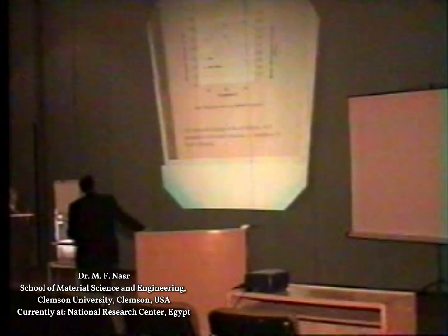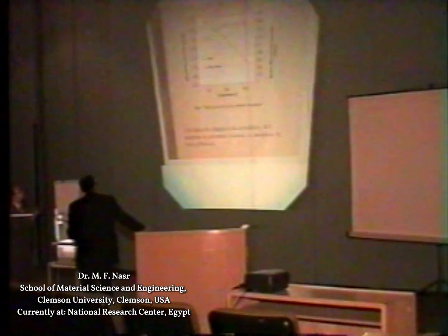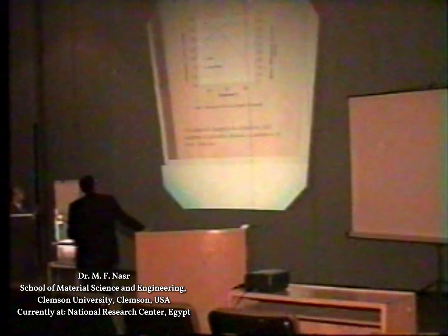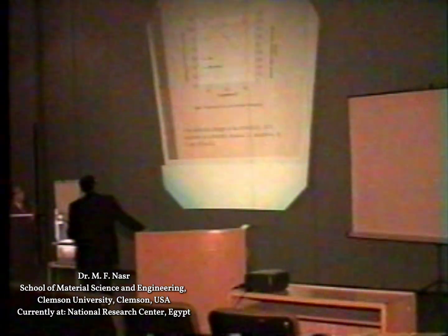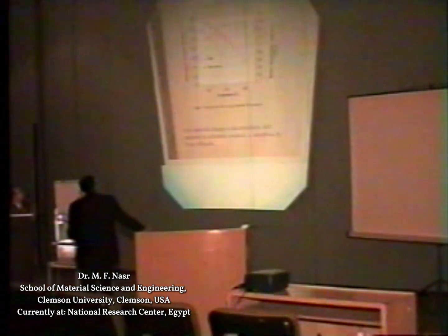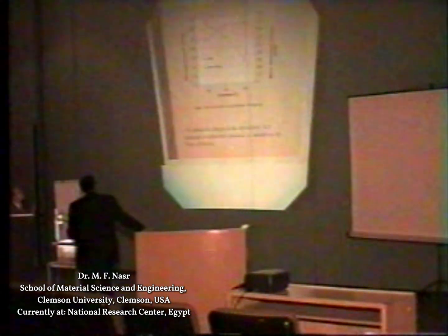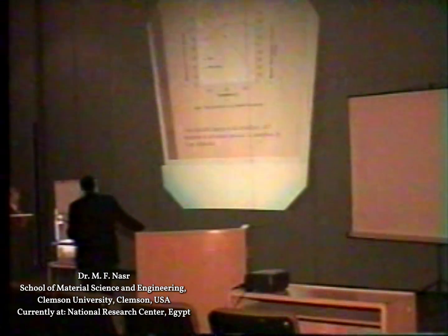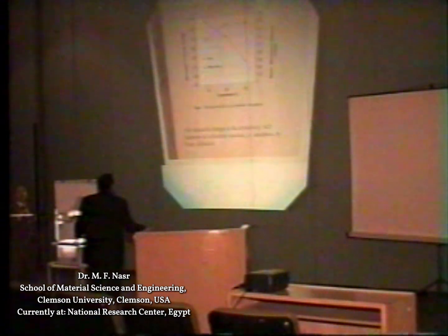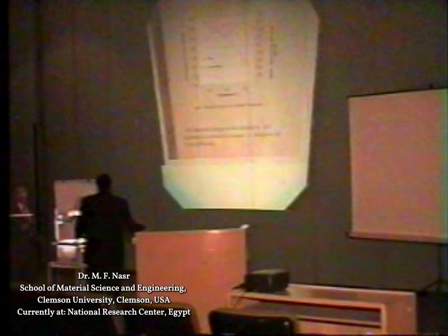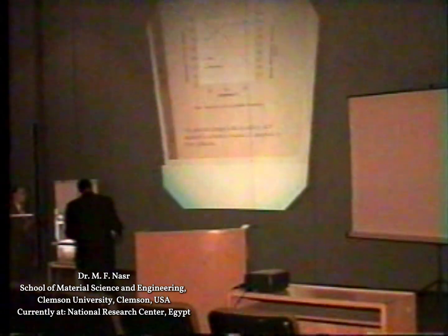And we also found a very interesting thing. We found that with the increase in the treatment temperature, the micropores start to decrease, while the meso and macropores start to increase and level off, which is of course kind of expected, because the micropores at higher temperature start to collapse and connect together. And that's why we moved from small pores to large pores, which is a good indication.